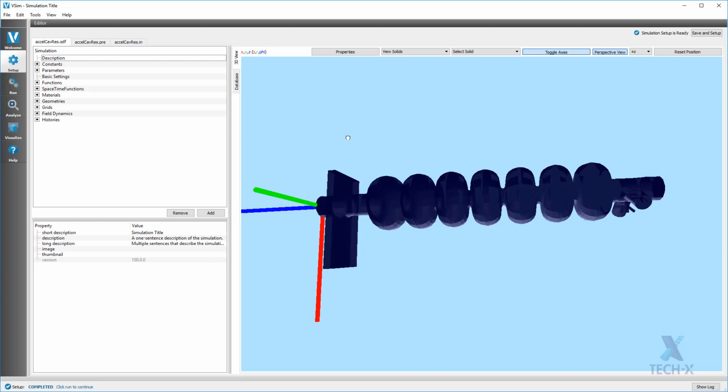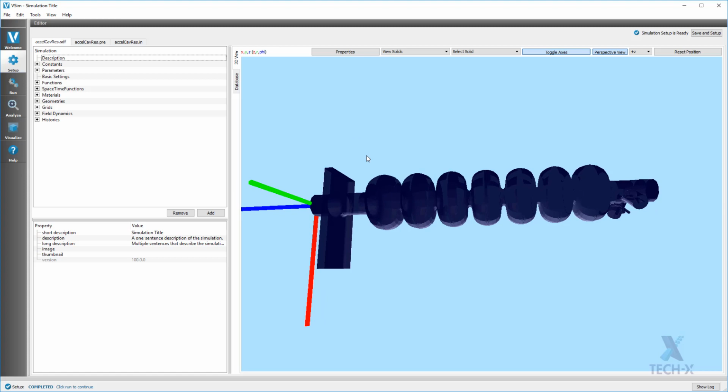In general, when first simulating an SRF cavity, we're looking for the fundamental frequency of the accelerating mode in this cavity. So to simulate a cavity like this in VSim, what we do is drive a current in the cavity that will create an electric field that resembles the resonant electric field we are trying to excite.